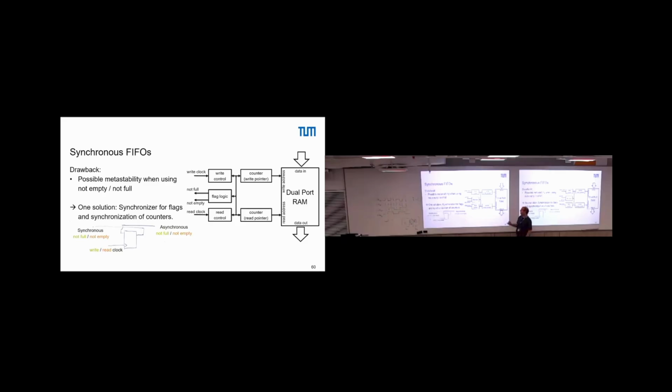So this is actually what triggers our logic flag, right? We have said we are in the cycle, right, where we have a read pointer and a write pointer. Read pointer and write pointer are counters, read counter and write counter. And we ask the question, are we larger, smaller, or equal?